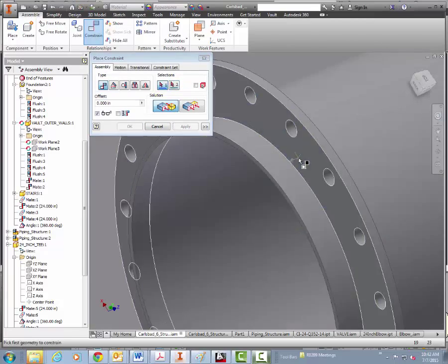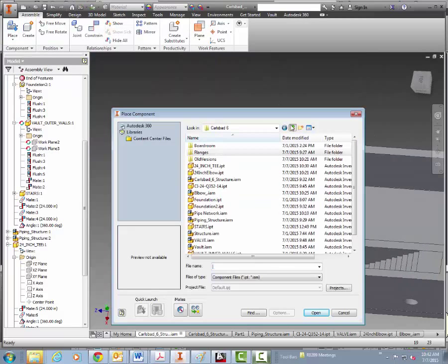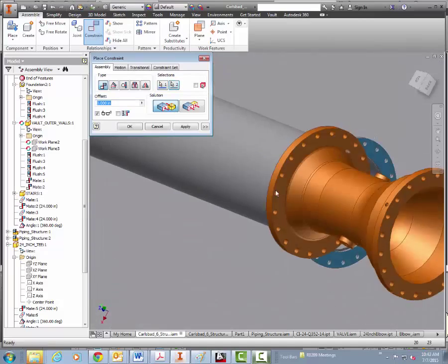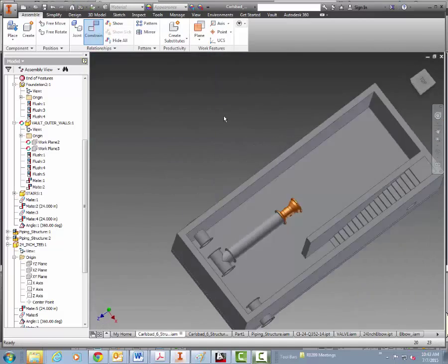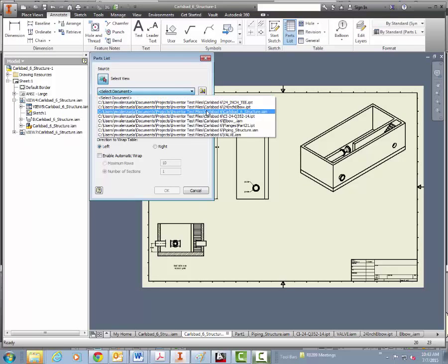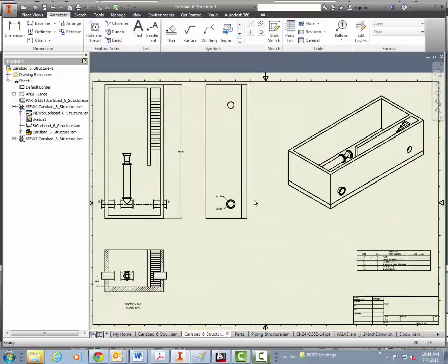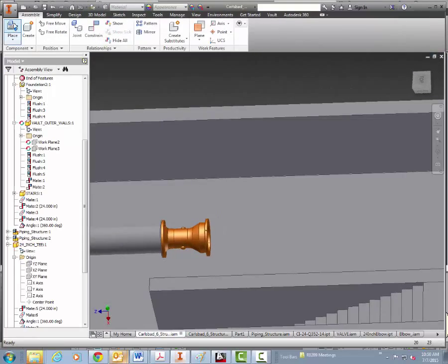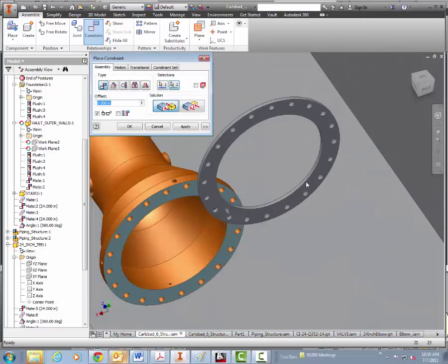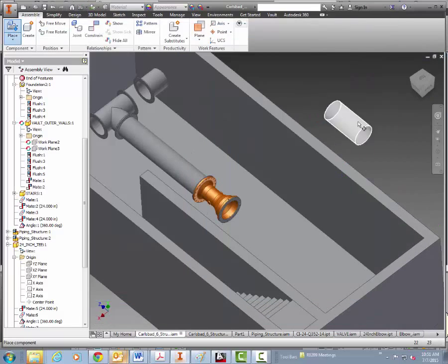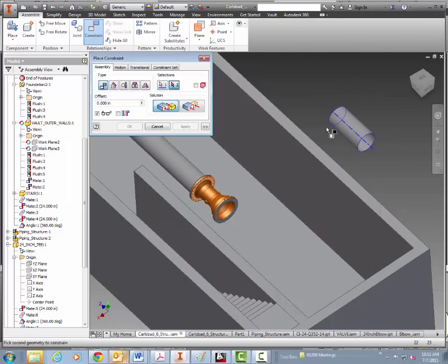Again, this is just like building with Legos. You're taking the components that are made in advance from the library that you created. And here's a standard, this is a Venturi meter that was actually provided by the manufacturer. Now we've added a BOM, or a bill of materials list, that is automatically updated based on the items in the 3D model. So every item that's added to it can be located in the bill of materials, so we can do takeoffs from it.